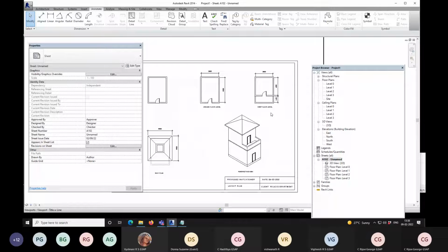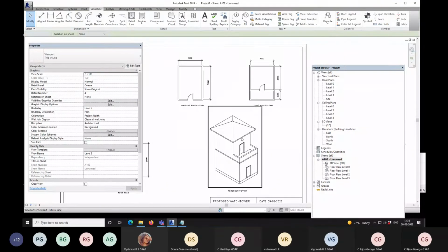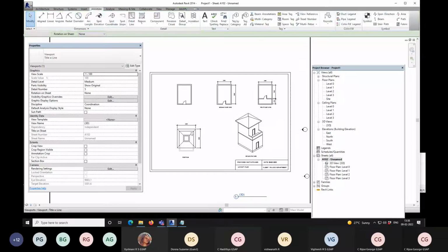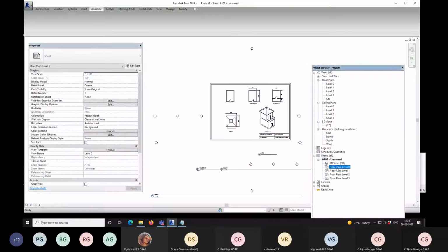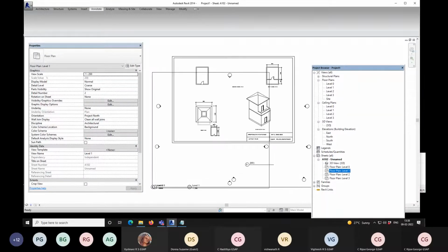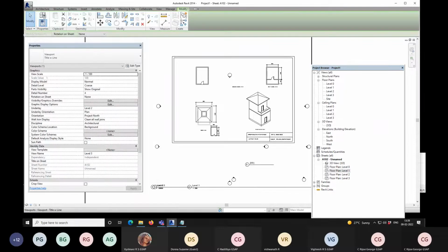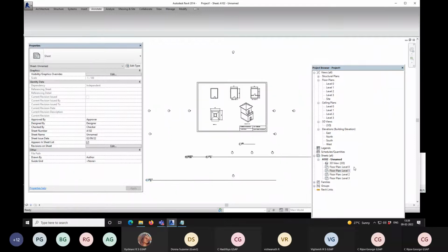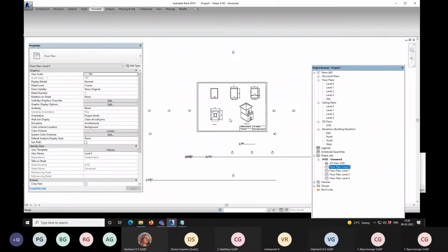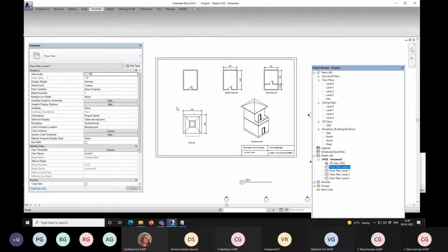But one thing you notice that whatever we dragged and we placed it here, this one is 1:100 scale. Everything is in one scale, 1:100 scale. Okay. So whatever we have dragged over here, if you select them, it tells the scale. If you adjust the scale, it is going to become small. See, it became so small and it moved here down. So it is here is where you keep the scale. In Revit, you just select the viewport and increase or decrease the scale. That is how it is.